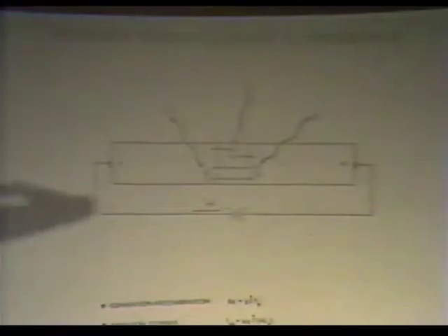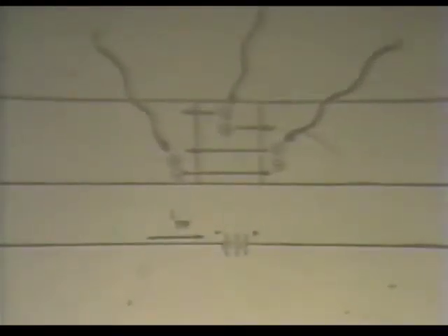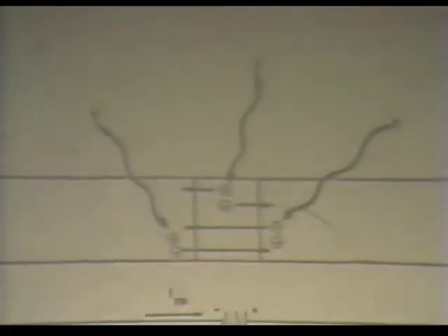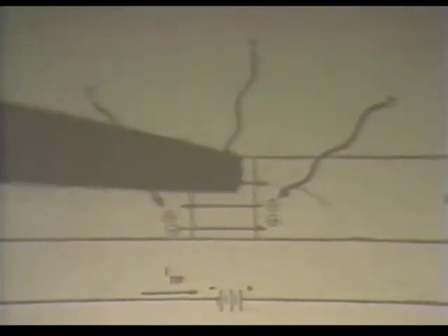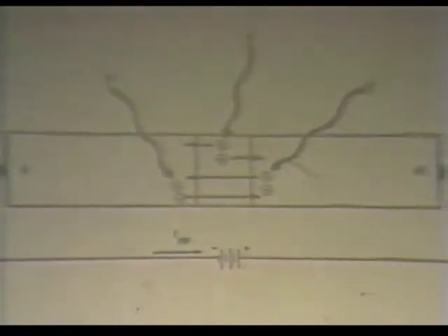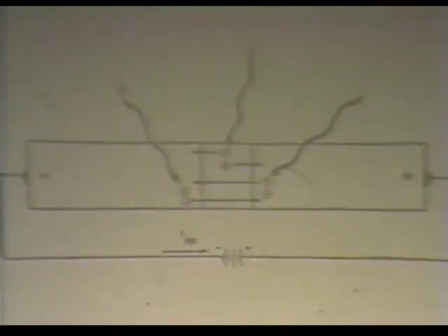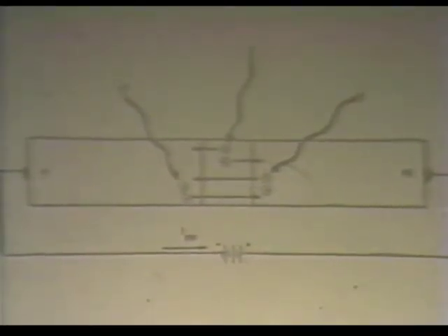Now let's illustrate this with a device. You know, the equations are there if you like equations, but what I want you to remember, here's a diode. You've got a p-n junction, you've got a potential here, so you're creating a depletion volume that I'm sure somebody has told you about already. And what happens? These photons going through that volume create just scads of electron hole pairs, and that device thinks, hey, somebody has turned me on.